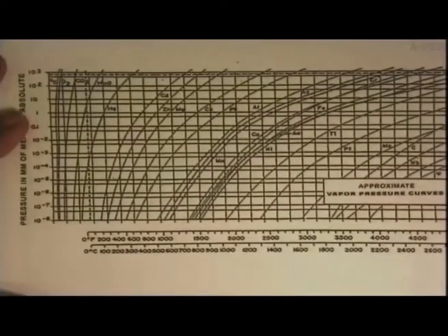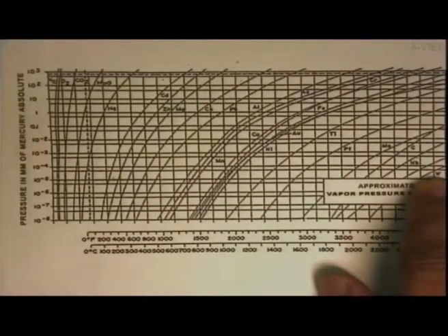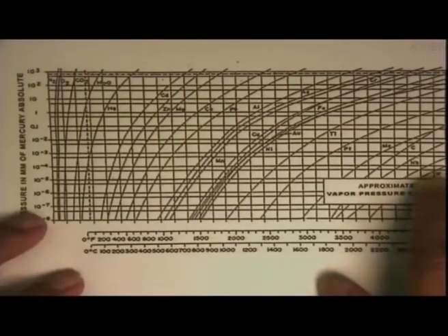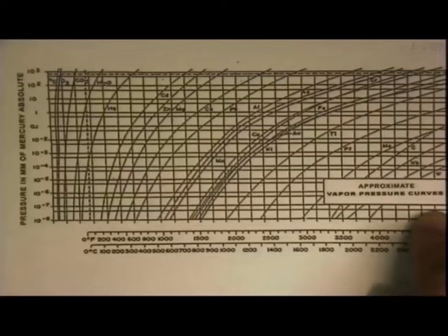And so one can ask, why do I need to look at the vapor pressure curve of, say, in this case, tungsten, W? Recall that earlier we had incandescent bulbs, and in the olden times the bulb was evacuated because of vacuum. So tungsten was heated to a high temperature, something like 2500, 3000 Kelvin. If you saw that the bulb goes fused, it is because the solid tungsten at that temperature kept evaporating, went into the vapor phase, the diameter of the wire kept going down, it got more hot, and at some point the bulb goes fused. That's what we say when the filament breaks.